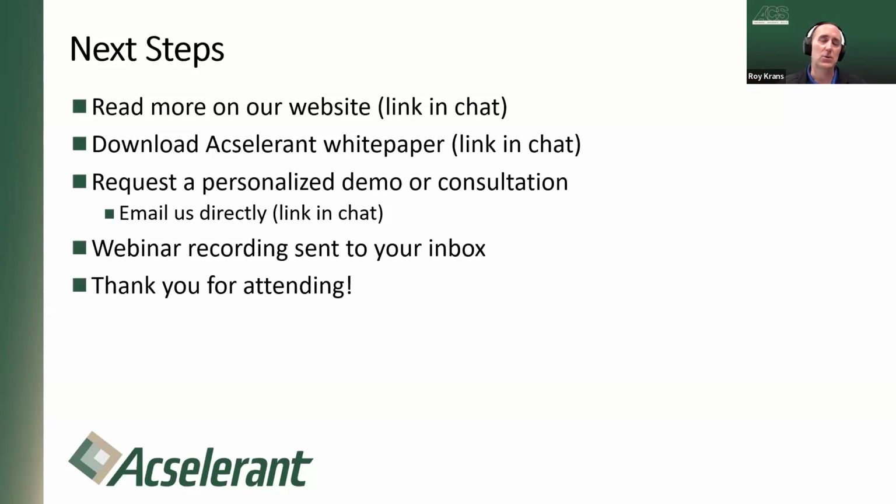For instance, in our test sequencer, we'll create a custom step that says, write this to the company database or read something from the company database. In those steps, you can create the edit screen and define how to connect to this database and how to read from it or write to it.